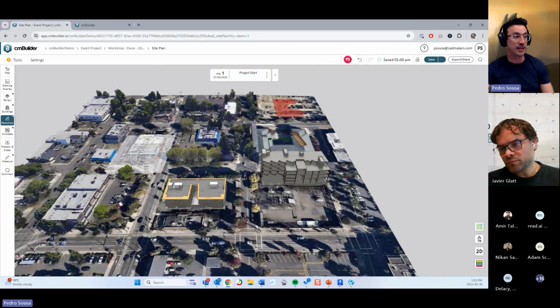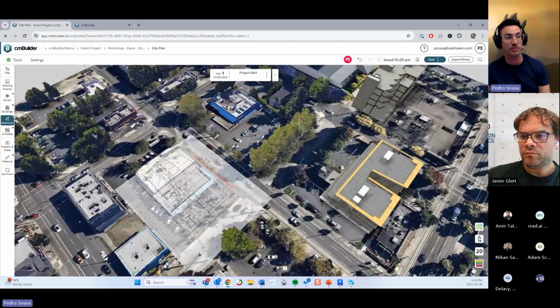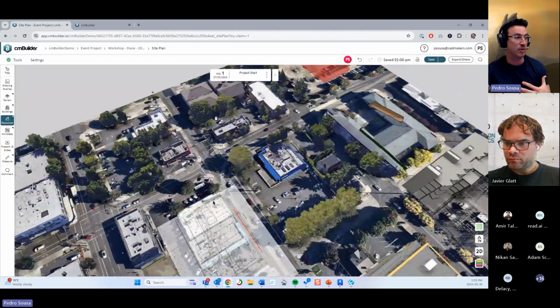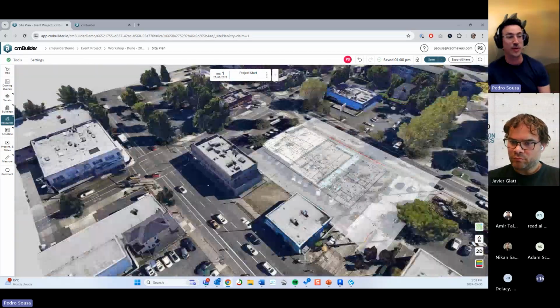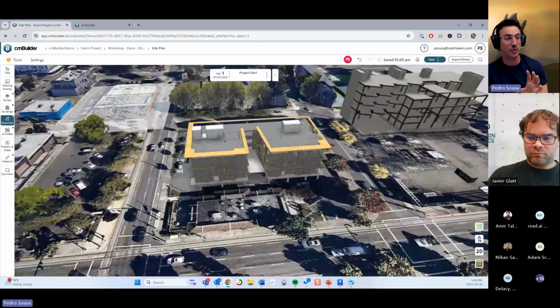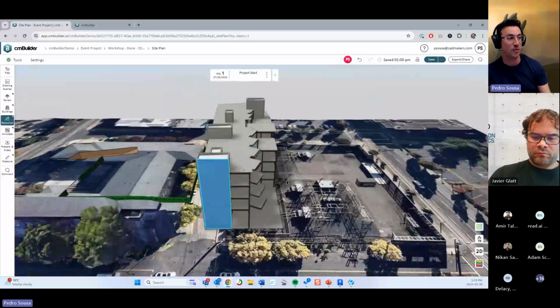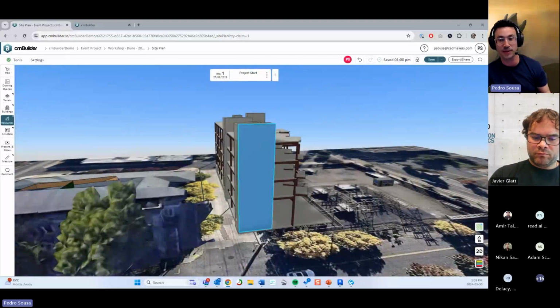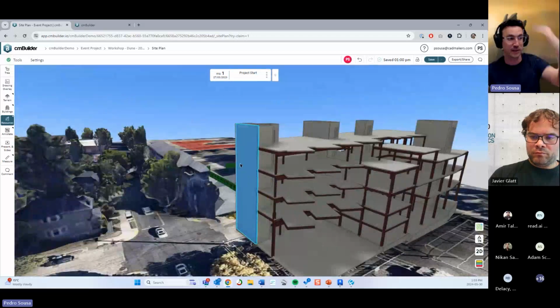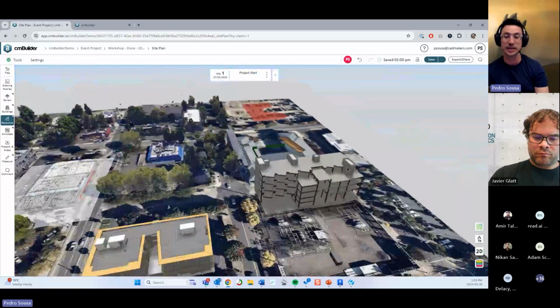And this is also something that will be used for drone scans, for example. You can create an opening and remove these trees, right? You can create an opening and remove this building over here, right? So the main idea for the split tool is to use it for pour breaks, to split elements like this, where you imported that element and the wall is just spanning the whole building height, and also to edit the drone scans.